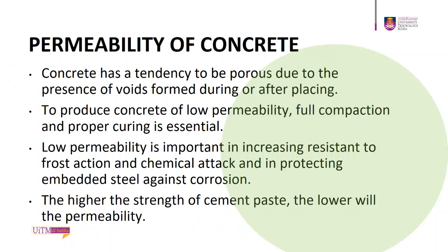To produce concrete with low permeability, full compaction and proper curing are essential, where low permeability is important in increasing the resistance to frost action and chemical attack and in protecting embedded steel against corrosion. So the higher the strength of cement paste, the lower the permeability.